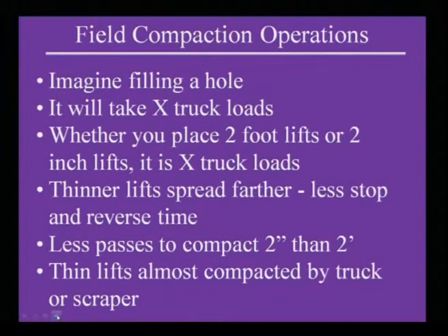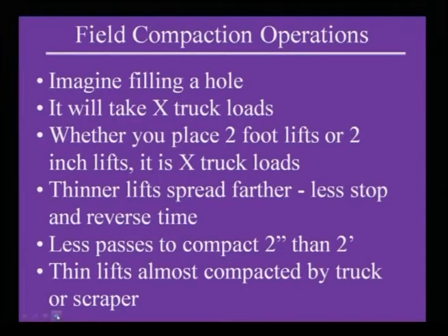In field compaction operation, just imagine you are filling a hole. It will take x amount of truck loads, whether you place 2-foot lifts or 2-inch lifts. Thinner lifts spread further, which means less stop and reverse time, and fewer passes to compact, so fewer passes will compact better. Thin lifts are almost compacted by trucks or scrapers.